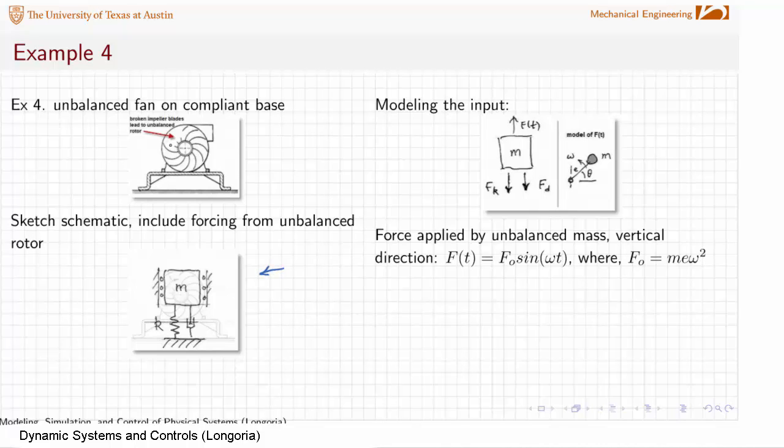So here we remember we had this fan that had an eccentric mass because of some broken fan blades. So that was going to be inducing a force. It's a rotating force, so it's actually an XY force if you think about it, in both directions here.